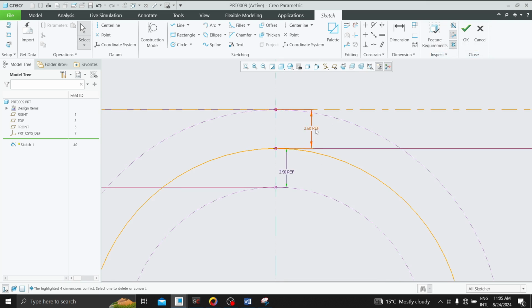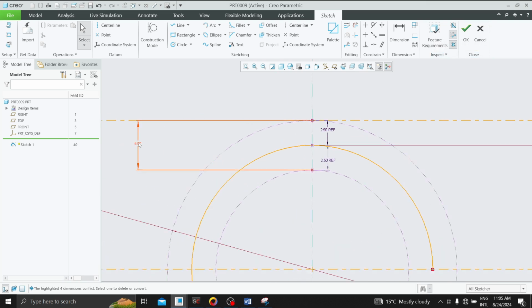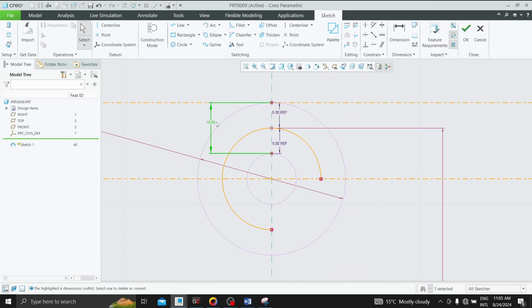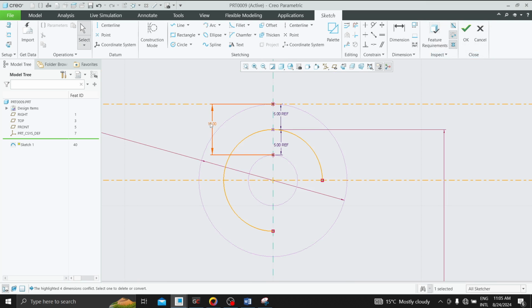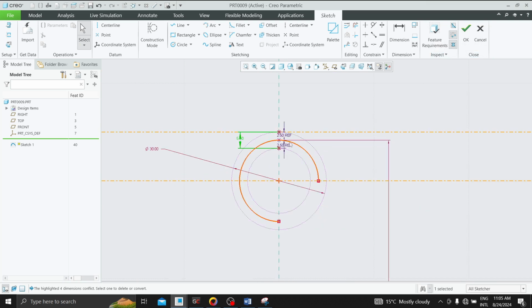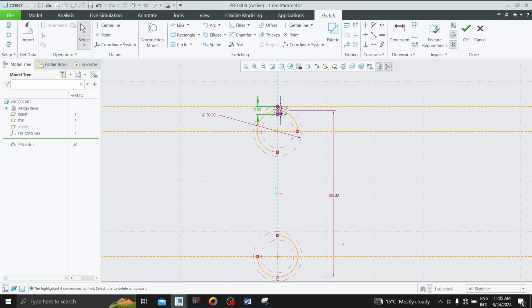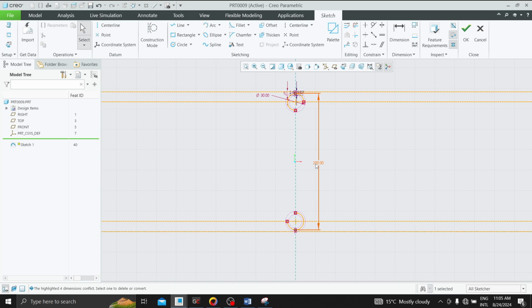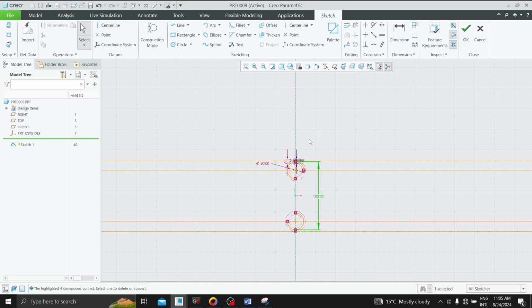Then I can delete that or make it a reference. You can see now it becomes from here to here 2.5, 2.5. That is being controlled by this 5. If this 5 changes to 10, this becomes 5. I'm just using this wire dimension to drive those. In the free length here, if I try this to be 200, everything is rebuilding without failure.